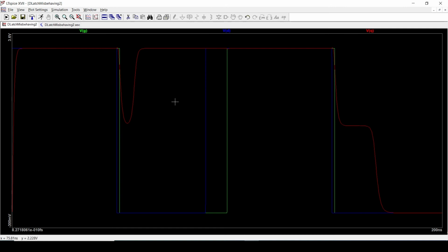We're not stuck if we immediately return to a logic 1 or drop all the way to 0. And both these states are valid in the sense that if the input dropped to 0 earlier, then the output should drop to 0 earlier. And if the input dropped to 0 later, then the output should stay a 1. So depending on whether the blue one arrived a bit earlier or a bit later, both outputs are perfectly fine.